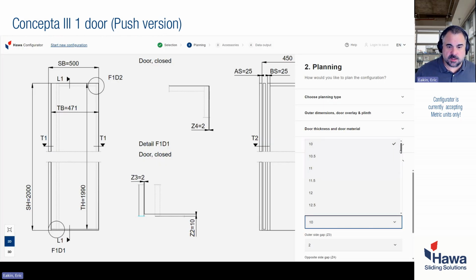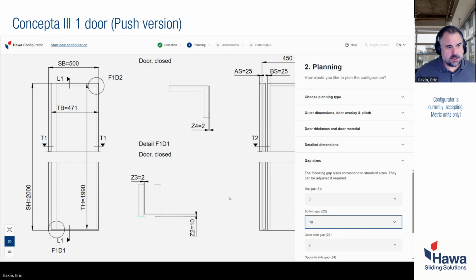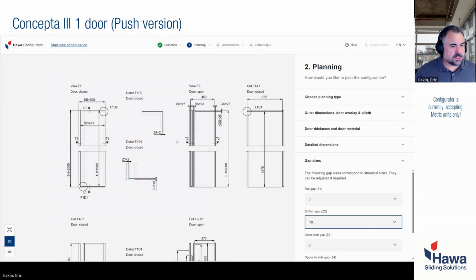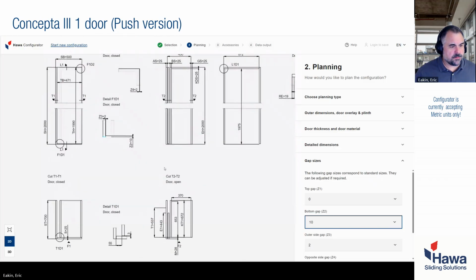If you want to keep something else in mind that's easy to add and subtract later on, you can do 12.5, which is roughly right at 1/2 inch. Or you can select, say, 25 millimeters or 25.4, being exactly an inch. And then you can just keep in your mind that you're adding or subtracting that from the door height later on. We're going to stick with 10 for now. And we're going to move on to the next measurement. In this next measurement, notice we looked at this earlier, the Z3 measurement.